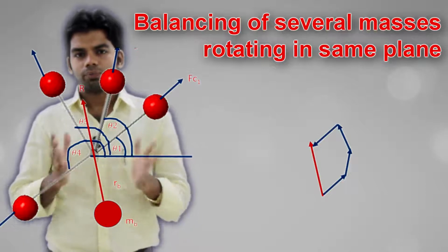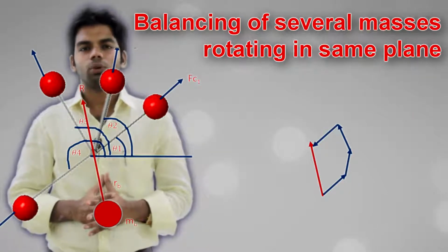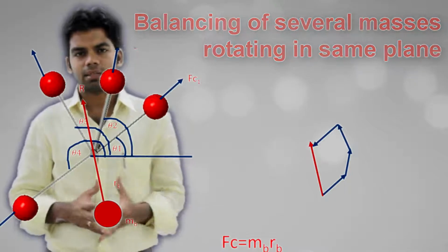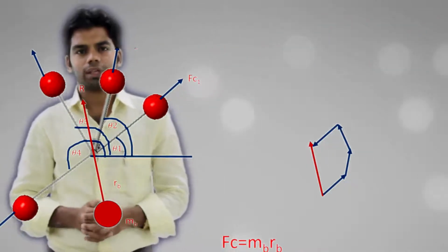For balancing, this Fc must be equal to mb into rb. So from here we can calculate the value of mb into rb, which is the balancing mass and the radius at which balancing mass should rotate. Getting this or not? Okay, so this was a graphical method to determine the unbalanced mass resultant and the balancing mass.